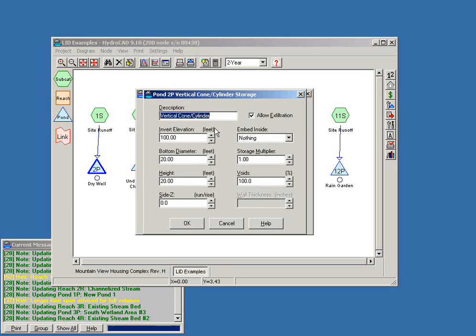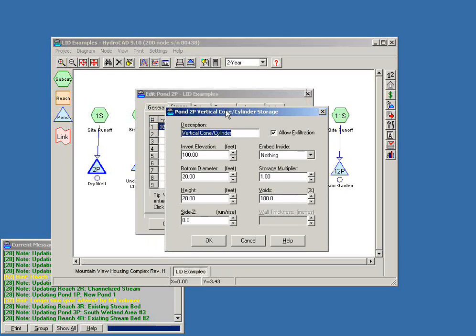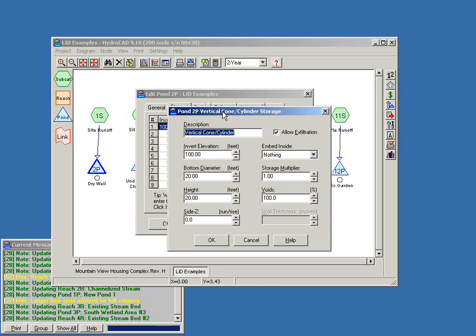Of course, you probably aren't going to have a dry well this size, but it does illustrate that you need a fairly large volume in order to deal with the typical runoff. Small dry wells that you might put under a downspout at home don't do very much for you when you're dealing with larger site modification changes. So the fairly large volume is provided in this example. We could also have storage provided perhaps in the stone around this leaching dry well. That would be another possibility.